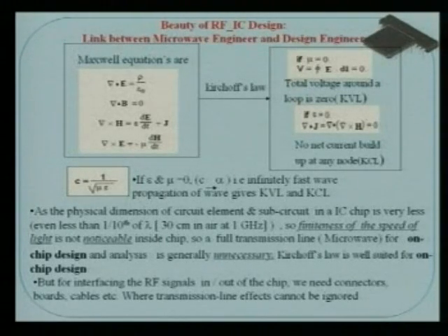For a vector, it is 0. So the divergence of J equals 0. Simple Kirchhoff's current law. That is, at any node, the total amount of current entering is equal to the outgoing current. There is no sink or source in the system. So I can jolly well derive the Kirchhoff's law from the Maxwell equation under special circumstances.